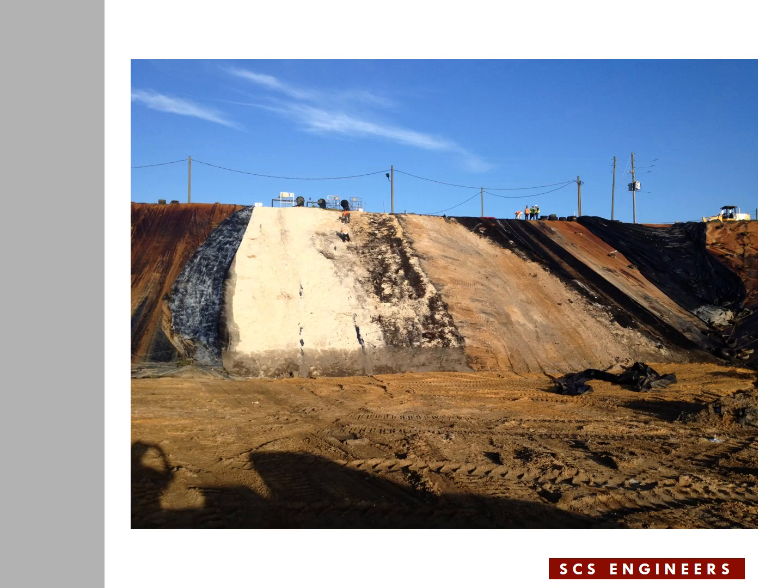This view shows the repair area. A little bit of explanation here where the actual repair area is in this picture. To the left side you see that white color area, that is the sand layer on top of the riser pipes that you see at the top of the slope. Geosynthetics of the lining system were below the riser pipes, and the sand layer above protected the geosynthetics in that area from the fire. But to the right side of that sand area, which is more an area with a tan color, is the damaged area.